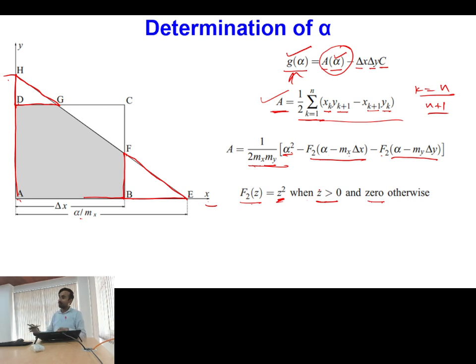Okay, so these are some generic formulas which you can utilize to calculate area once you have placed this line at any arbitrary location. Once you have calculated this area, you have to minimize this function g of alpha to determine the exact value of alpha for which this condition is satisfied. Are all clear with this point? Of course, you cannot make this completely 0 because of numerical computation. So, the way you specify residuals for your continuity and momentum equations, in a similar way you have to specify some convergence criteria for this function also. Okay, and then you can reconstruct the interface profile.